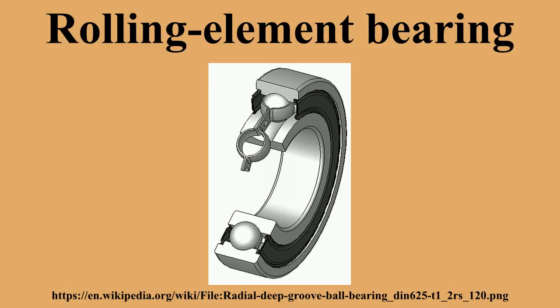The fourth digit defines the type of bearing: 0, ball radial single row; 1, ball radial spherical double row; 2, roller radial with short cylindrical rollers; 3, roller radial spherical double row; 4, roller needle with long cylindrical rollers; 5, roller radial with spiral rollers; 6, ball radial thrust single row; 7, roller tapered (also heavy vehicle bearings); 8, ball thrust radial; 9, roller thrust radial.